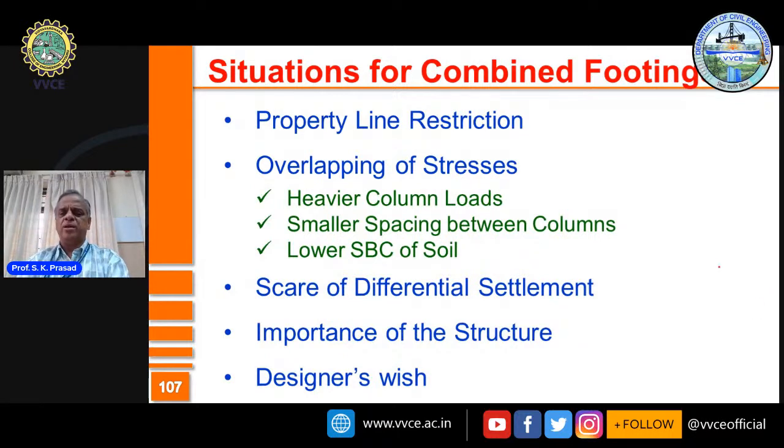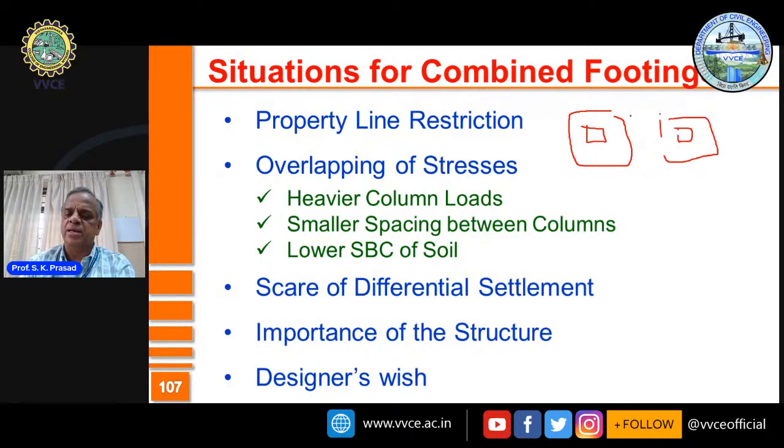What is a combined footing? You have one column here, you have another column here. You cannot provide isolated footing like this. You cannot provide isolated footing like this. Instead, you're going to combine these two, put together and put one single foundation.